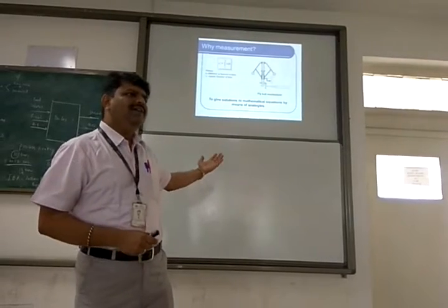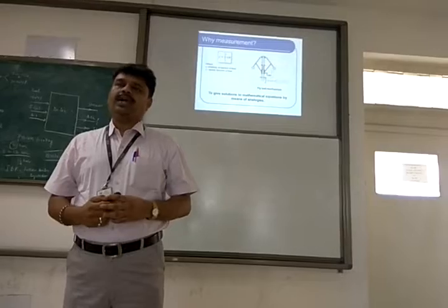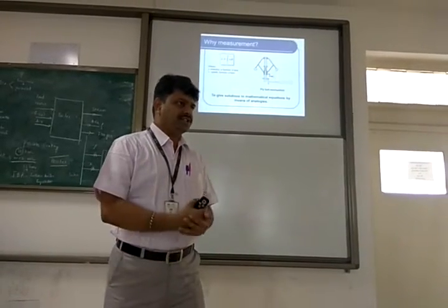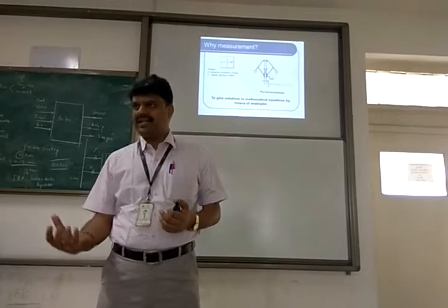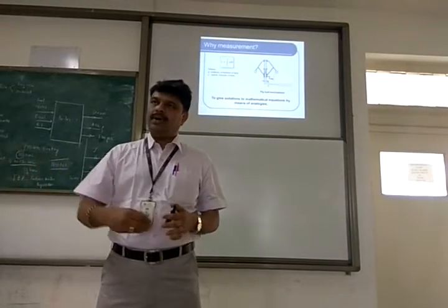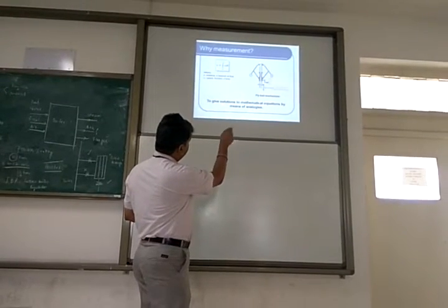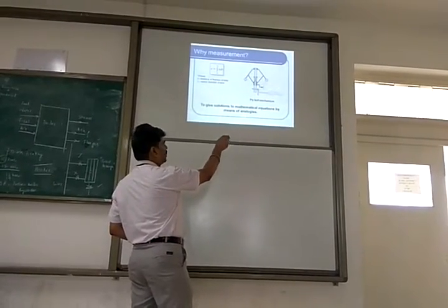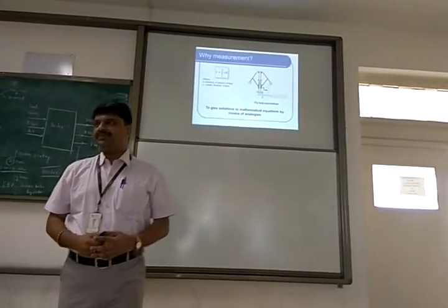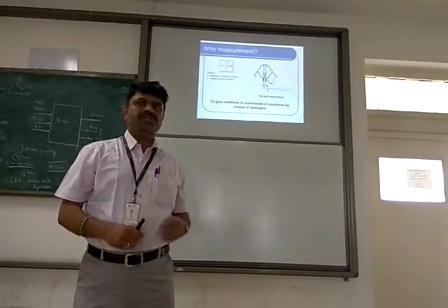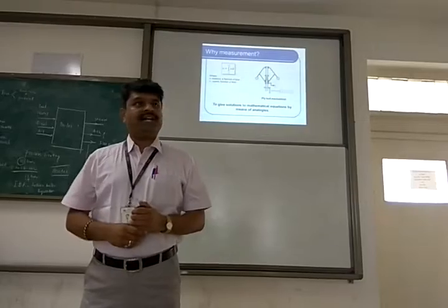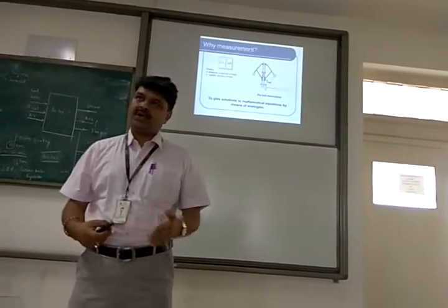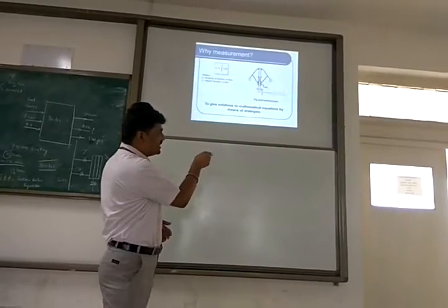Now, sir, what is the linkage of this to measurements? There are some mathematical equations for which direct integration is not possible. If you have such a complex expression, you link that expression to the velocity of rotation, and then this reading will give you the integration value from T1 to T2. In olden days people used this method as integration by analogy. They don't use actual mathematical functions. The mathematical function is converted into a proportional voltage to the motor, which rotates this shaft, and you take the reading as a proportional value.